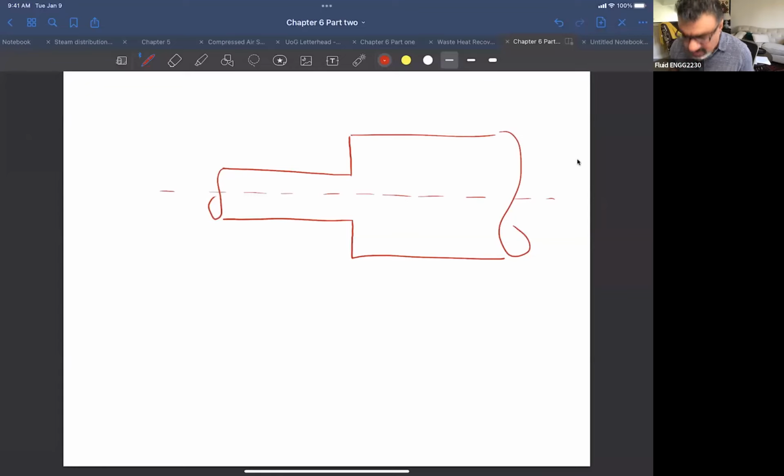And this is a center line. What's going to happen here, in order to describe the flow, is you are considering the flow is moving in a streamline. If you remember the streamline definition that we discussed in, I think, chapter 5, those streamlines are not real lines. It's just a line that represents the velocity, tangent to the velocity vectors, right? So if you imagine the flow is moving in lines like that, those streamlines, when moving in a pipe, will not change sharply like this. You can't have a streamline like this.